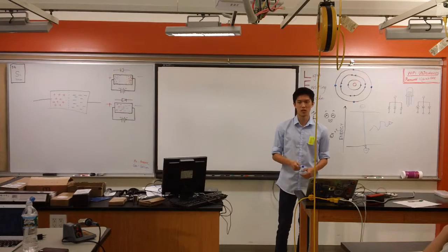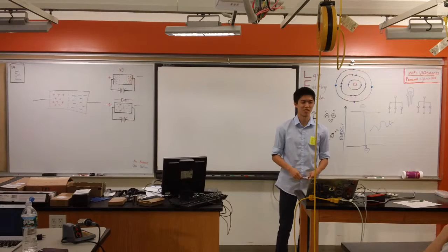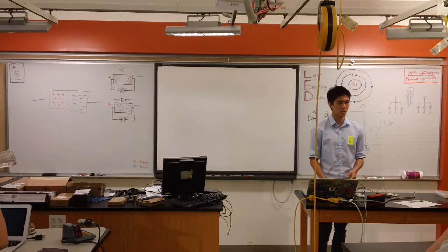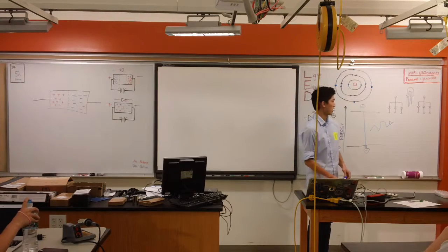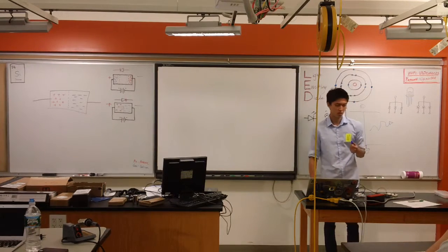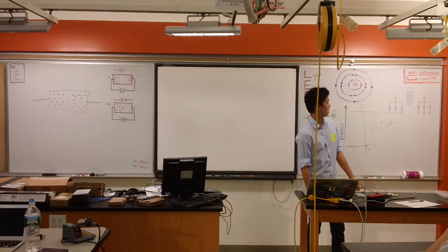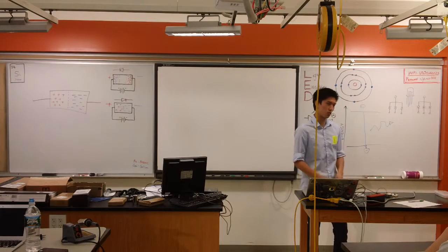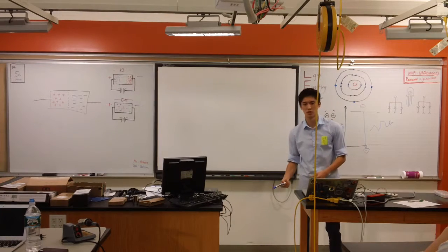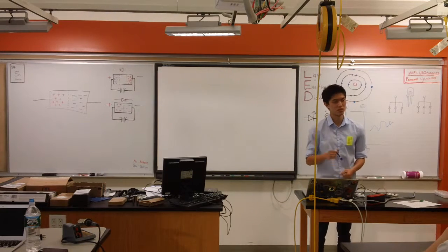Who's used an RGB LED in their product before? Oh, you guys, I know you got an RGB LED, right? As you probably figured out, there are two different types of RGB LEDs. You have common anode and common cathode. So I drew them here. I'm trying to point out that you hook these two things up differently, and you apply power to different ends of the LED, and you have to ground the other side, depending on what type of RGB LED you have.